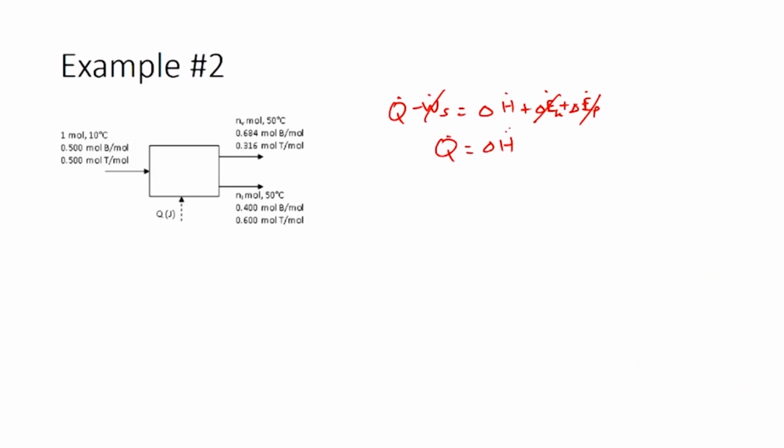For building the enthalpy table, we need to have the reference states for benzene and toluene. So, we will have to prepare the reference states for benzene, toluene and also account for the phases of these, which means we would actually have 4 distinct components when we build the enthalpy table. We would have benzene liquid, benzene vapor, toluene liquid and toluene vapor, and we need to make sure all are listed separately while we build the table. However, when we choose the reference state, we will choose one reference state for each chemical component separately. So, we will have one reference state for benzene and one reference state for toluene.